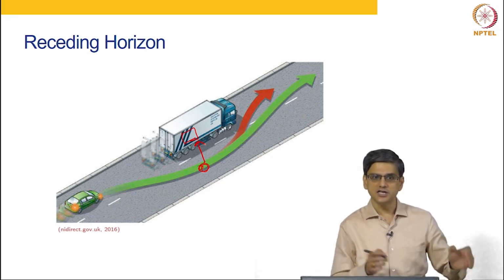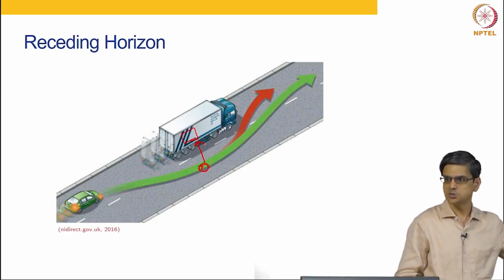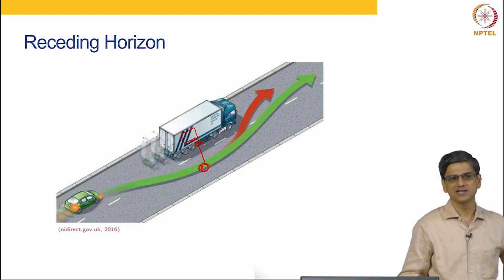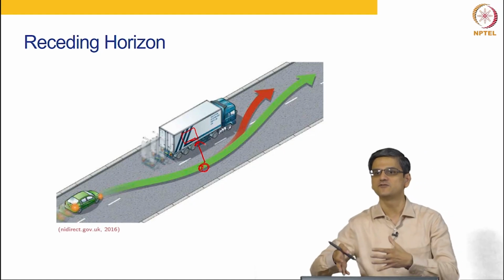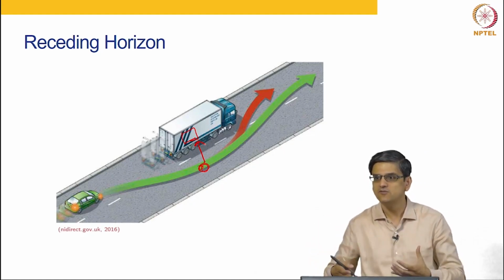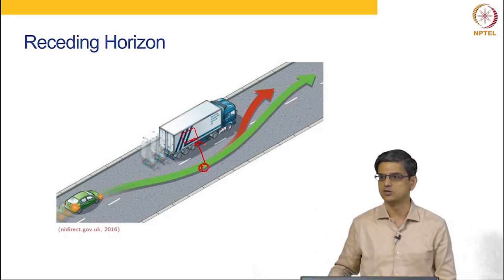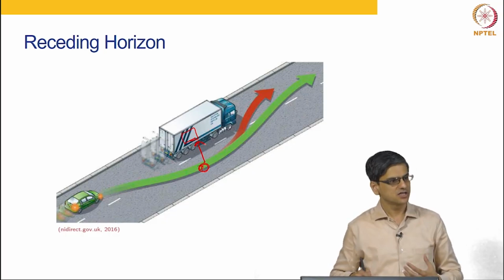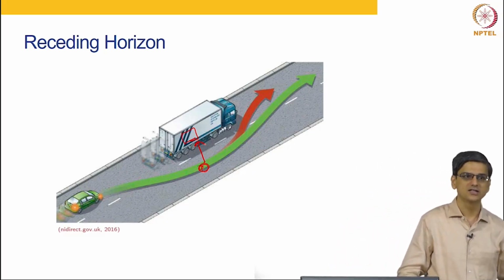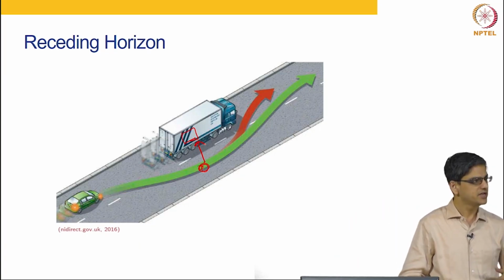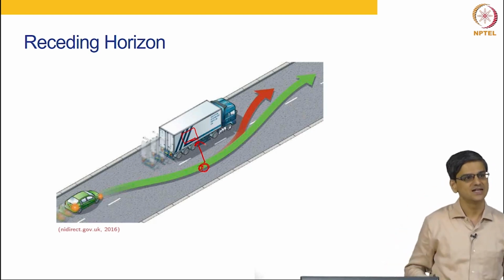Your traditional control was basically about the location, about the history, and you are integrating over the error in some way. So there was no prediction of behavior involved in your PID control, or your on off control, or your ratio controls and things like that. This is something unique to MPC, where you are predicting the behavior, and in order to predict the behavior you do not only need the sensor information, but you need the information of the entire state.